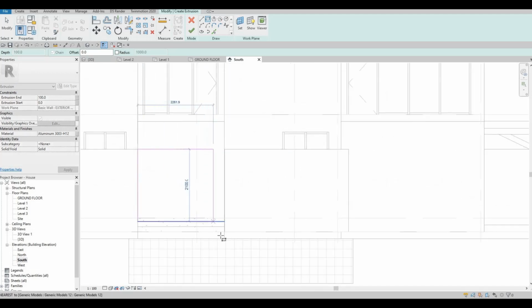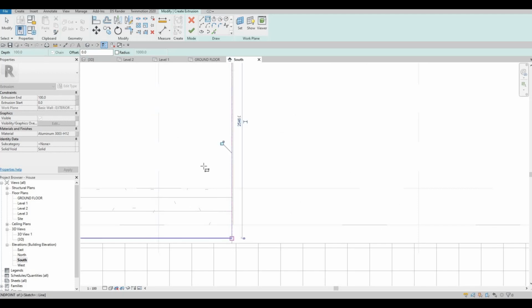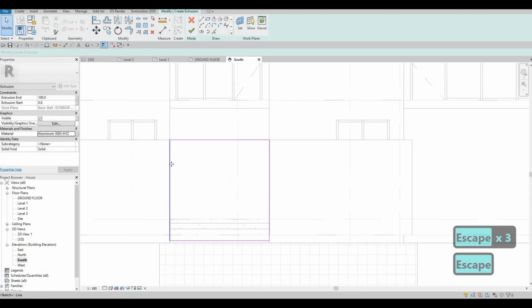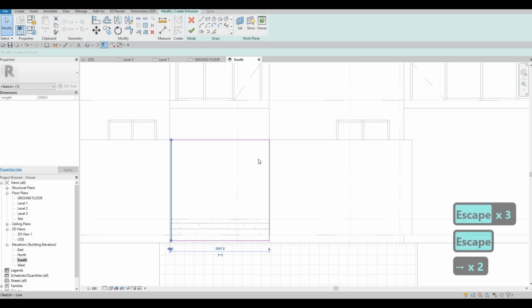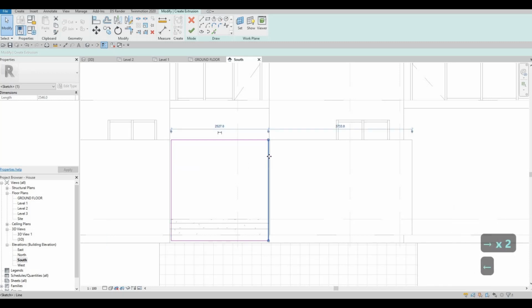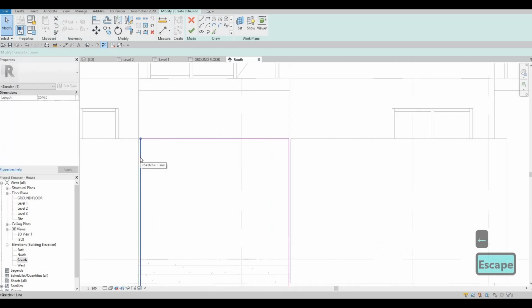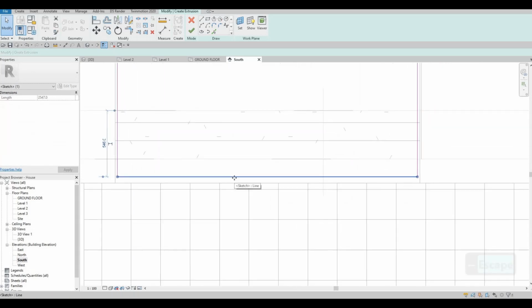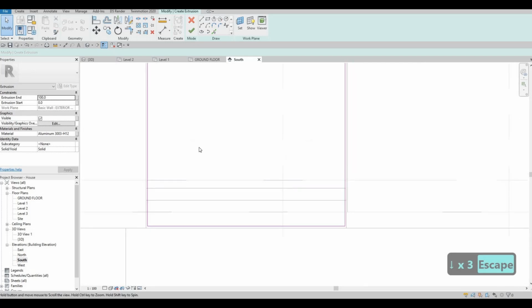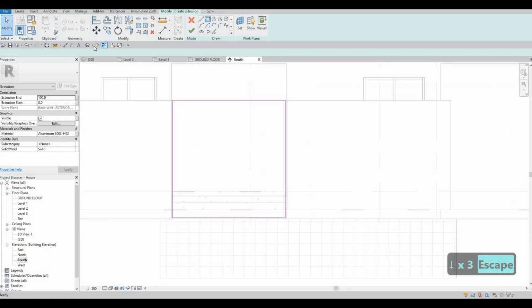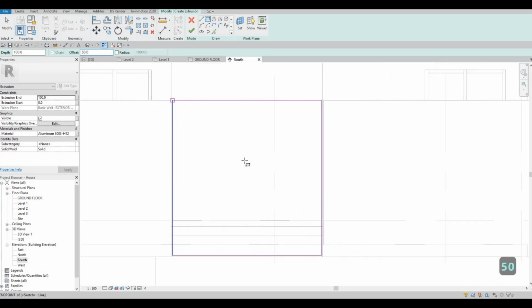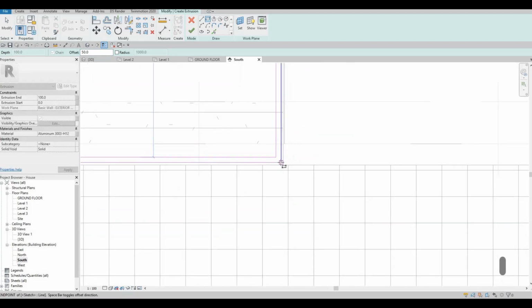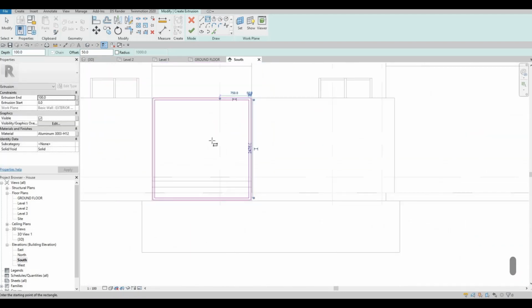And then after that, select rectangle, and then obviously we need to add rectangles right here. And then before we do that, we need to select here and then nudge it a little bit on the side. The reason for that is obviously we have some hinges there, so I don't want to give it too much of that without gap, so that's why I'm doing this, to make it look realistic enough. And then here we could offset this to probably 50, and then select spacebar in order for your offset to go inside. After that, click on finish,